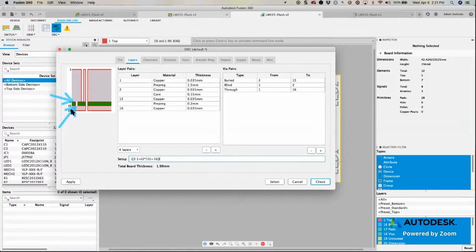Now this process, as Jorge just mentioned, is very expensive, because now it's a via that you cannot see. Now, why would you do this? Again, it's to save space. If your board is that dense and it needs to be that small, it may require buried vias, as you could see. Now, the process is kind of expensive. In addition to that, the process for troubleshooting is quite elaborate when you have buried vias on your design. So they're not really easy to have on the board.